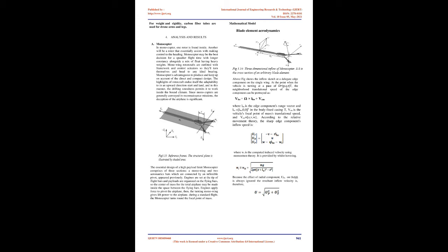The designed component can then be moved to different analysis software by converting them to different formats like STP, IGS, and so on. For the project, the wireframe and surface workbench was utilized. A 2D sketch was drawn utilizing Sketcher, then converted to a surface in the wireframe and surface workbench.